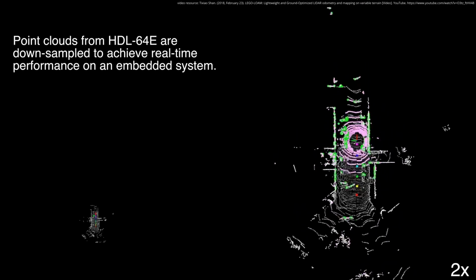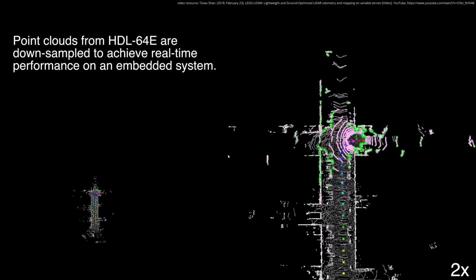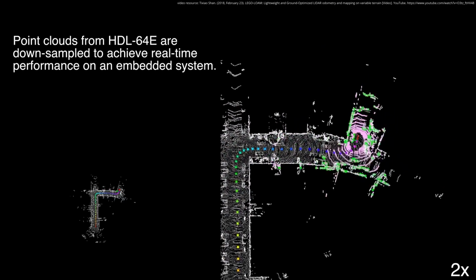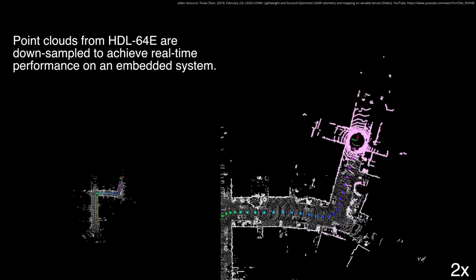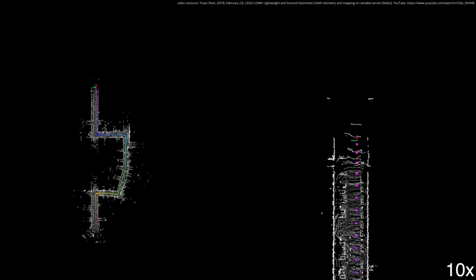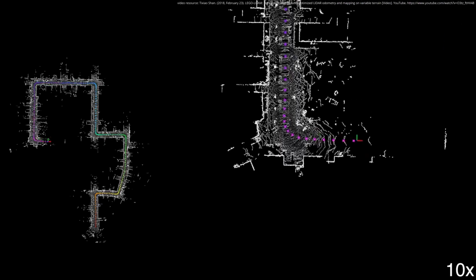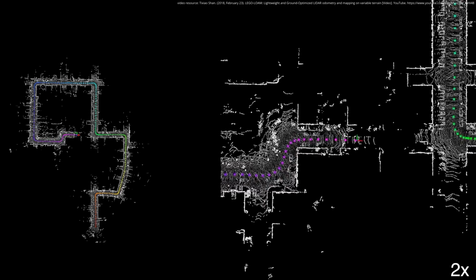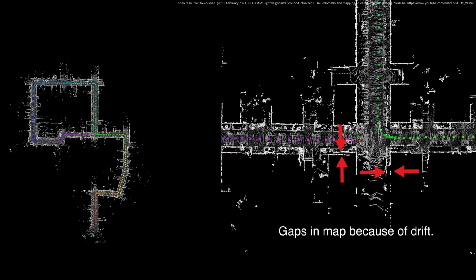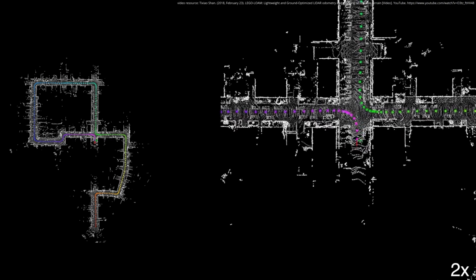In the last experiment, the loop closure functionality of the LiDAR mapping module is tested. It is demonstrated using the KITTI dataset from the Karlsruher Institut für Technologie. The iterative closest point algorithm is leveraged for adding constraints between the nodes in the pose graph. The subsequent optimization is realized with the iSAM2 algorithm. Because the KITTI dataset was recorded with another LiDAR scanner than the one which was used in the previously explained experiments, the number of points has to be reduced so that the amount of data to be processed is comparable to the previously captured point clouds.